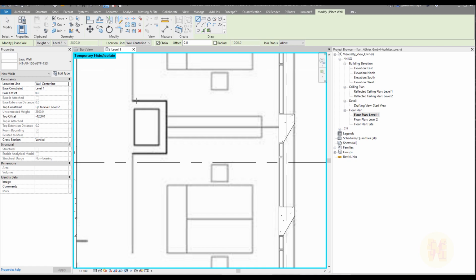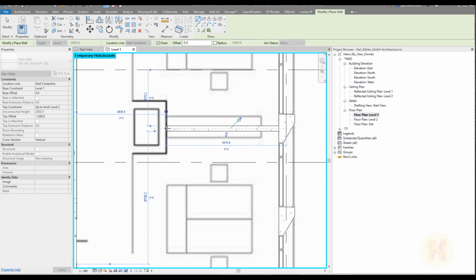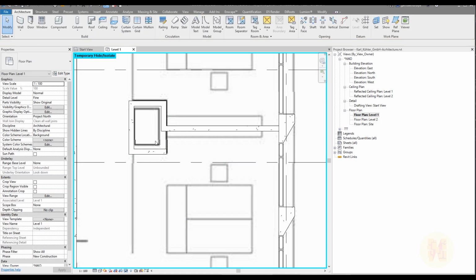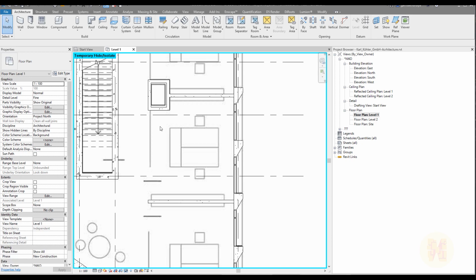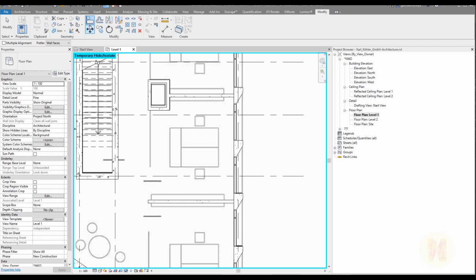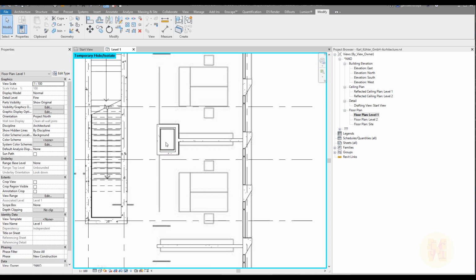Here we have the shaft, as you can see. I can see the shaft exactly, and I will use 300 millimeter. After that, I will change it to the exterior one, and I will draw my shaft here. Because we are doing the replica, I'm doing approximately everything. I will use TR, which is trim, and I will trim all of the things. Now I will use align, which is AL, and let's align my shaft. As you can see, everything is alright.